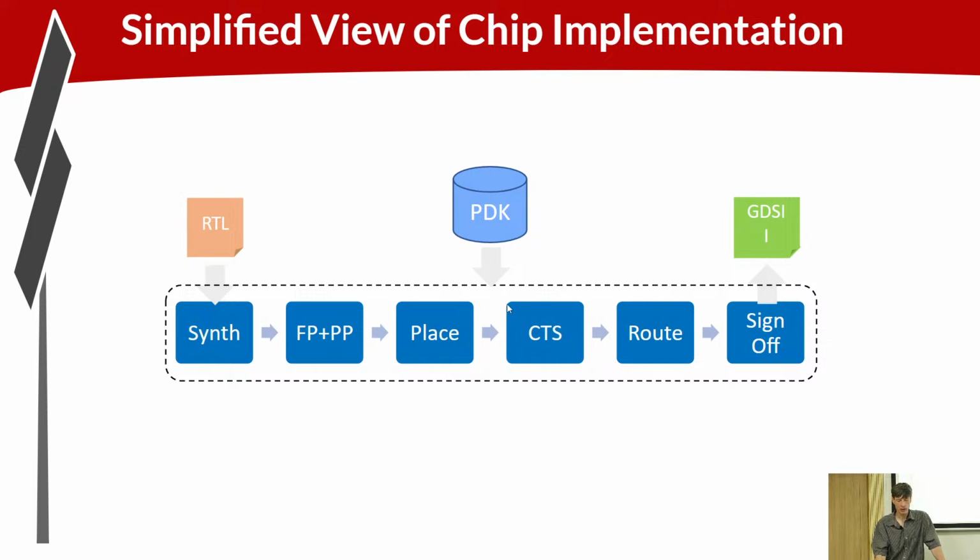Clock tree synthesis is how you're delivering your clock to all of your logic. Routing, so you've got your cells at the lower level, metals, and you've got your interconnect above that. Routing is all these upper level metals that are connecting up your cells.